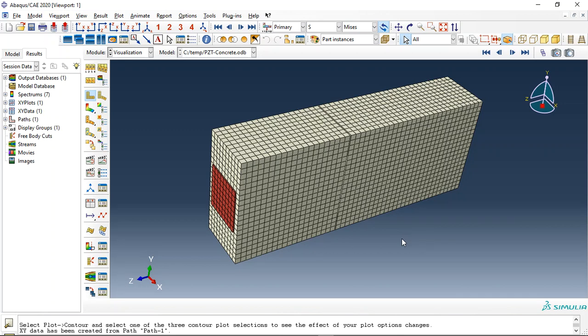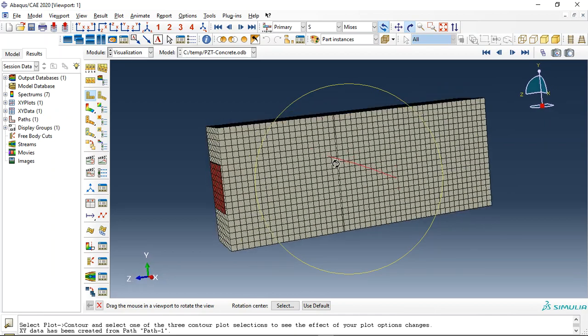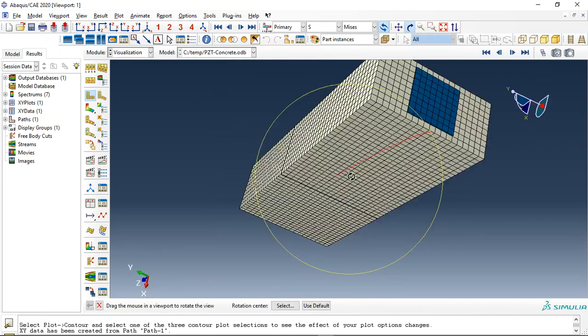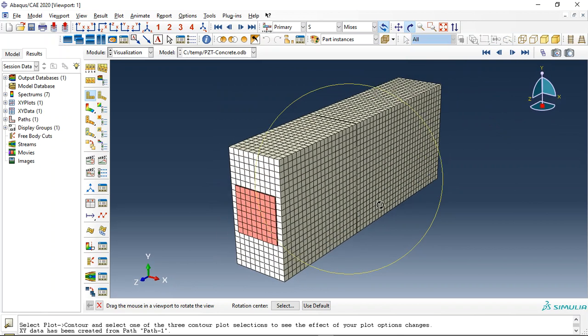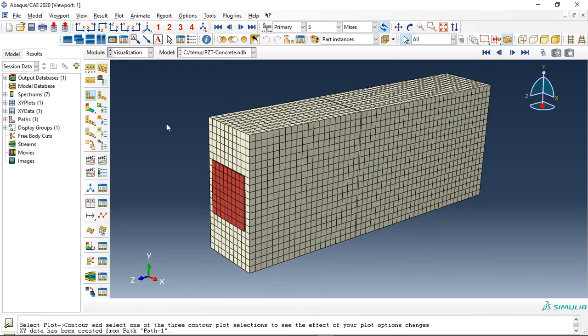Today we did a model of the damage and crack identification by using piezoelectric or PZT of a concrete beam. You can see this is a concrete part here, and we have two PZT, blue and red, at the left and right of the concrete, and we applied the load. The load can be electrical potential, displacement, force or pressure on the piezoelectric, and then the piezoelectric converts that. If you apply electrical potential, the piezoelectric converts that to displacement,